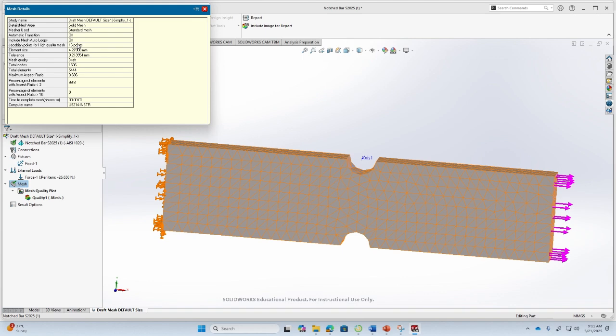For linear elements, normally we do not have the nodes on the middle of the edges. You only have the nodes on the vertices, okay? But even for the linear elements, you can introduce nodes on each of the faces. What it does is it increases the number of computational points again, and therefore allows for better calculations, okay, and better integration for the average results for each of these elements, okay.